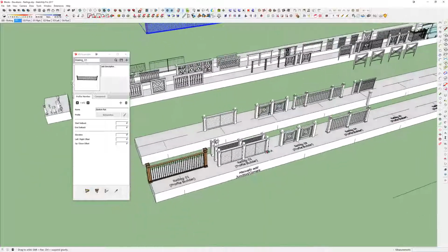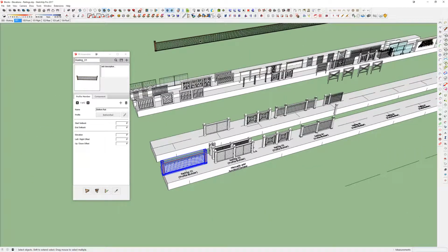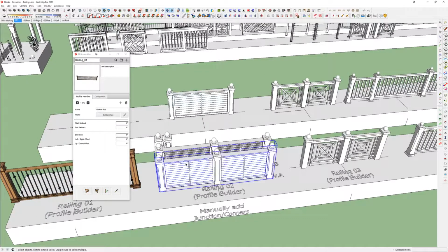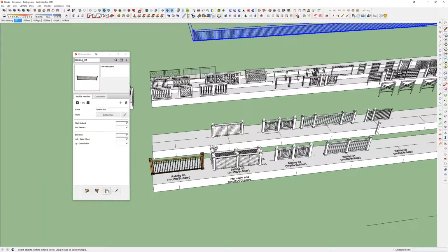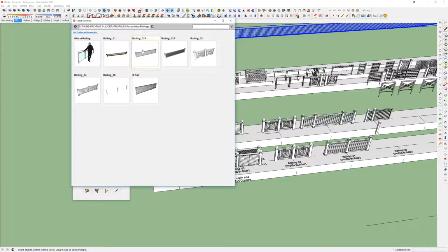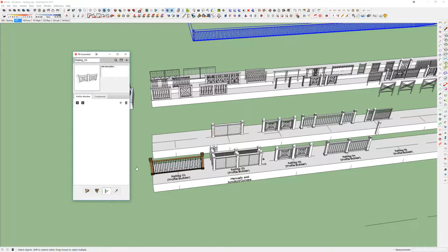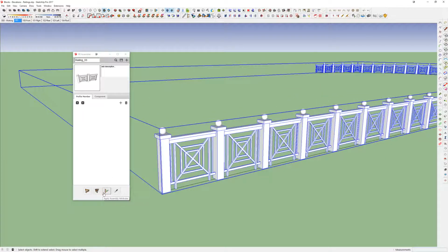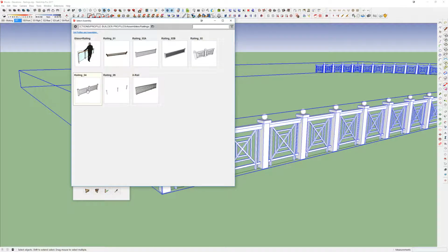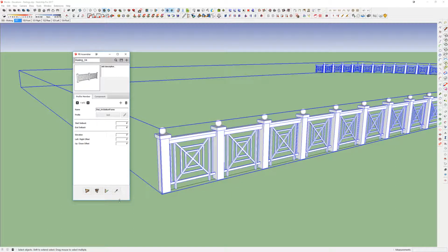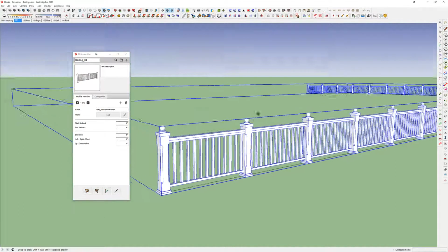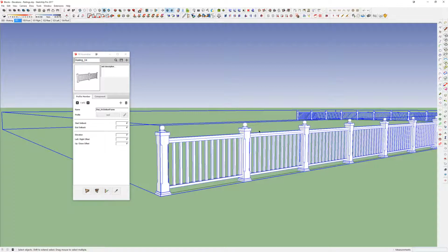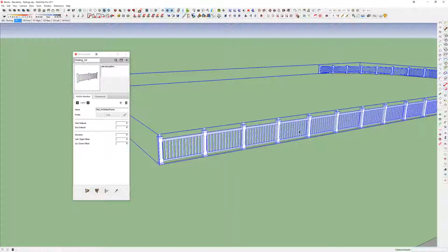And that's what all of these railings down here are. You can see this one is just that one that we just built. But I also have some of these other railings already being worked on. And I think I can reload that railing with this railing. So you can see just this quickly, if you build them using this parametric modeling, I can really change out these railings pretty quickly. So I'll select this design and switch it over. So hopefully you guys are seeing that, just how quickly you can build these railings.